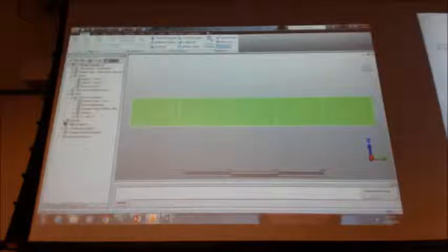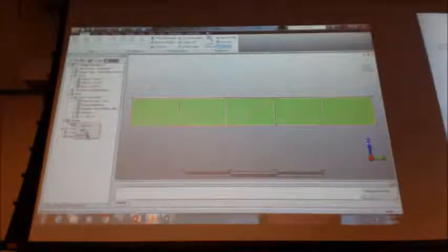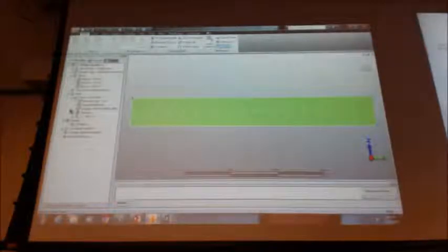So to force that, let's see, edit, we want to delete. We know that our beam here is 1 inch tall. So if we say that our elements are 0.5 inches tall, we say apply. Now we get 2 elements to span the width of our 2D model. And to apply loads, it's the same as what we did before. You're on vertices.